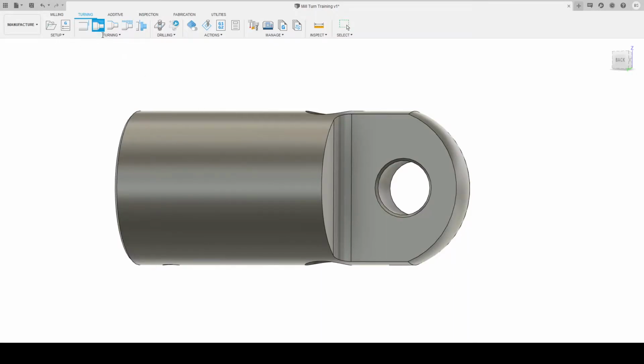You can fill out all this if you like, but for today and for everything you do, it won't be necessary. Mainly you'll be selecting from tool libraries anyway that are pre-created. So for today we'll jump straight into insert. Typically we'll use a WNMG, and for roughing we'll use a 0.8 corner radius. Everything else we can leave all good.